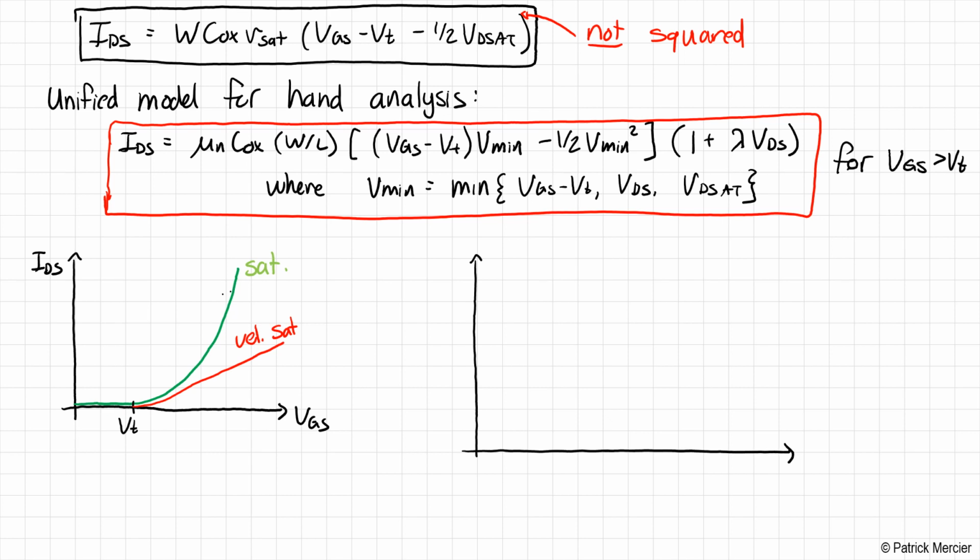So what I'd like to plot now is IDS versus VGS. Okay, the previous plot was IDS versus VGS, and I'm sorry, I want to plot this not versus VGS, but versus VDS. Okay, so this is versus VDS. Now normally we expect this plot, perhaps I'll use green here. Remember, we start off in the linear regime, and then eventually we kind of saturate. Maybe there's a little bit of channel length modulation going on here, etc. It usually looks something like this.